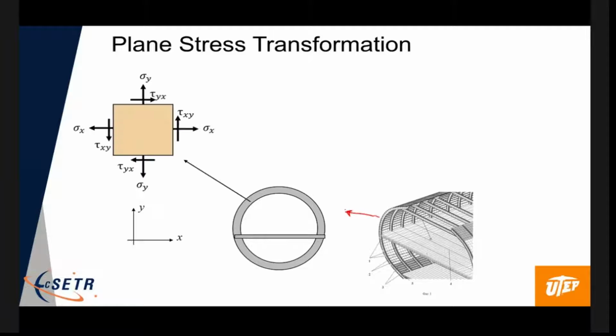And let's see what else we got here. So if you were to look at a point on that bulkhead, right? And we've seen this actually already when we talked about some of the combined loading problems. Let's say you do either a finite element analysis or you can do it by hand. You get a state of stress. There it is. There's a planar state of stress. We have a normal stress in the x direction, in the y direction, and an in-plane shear stress, okay?